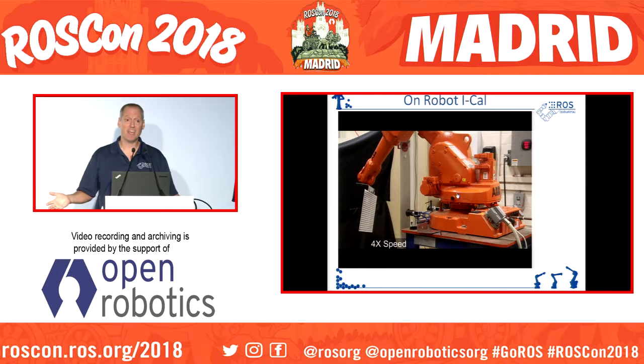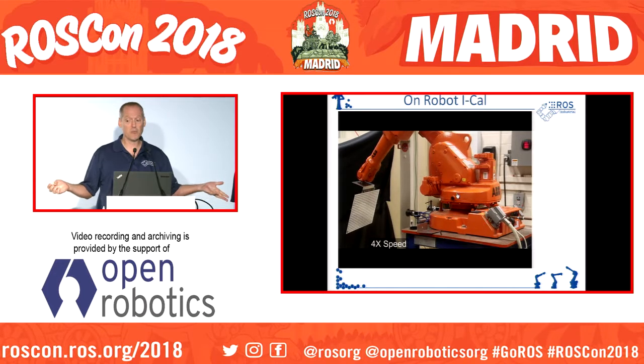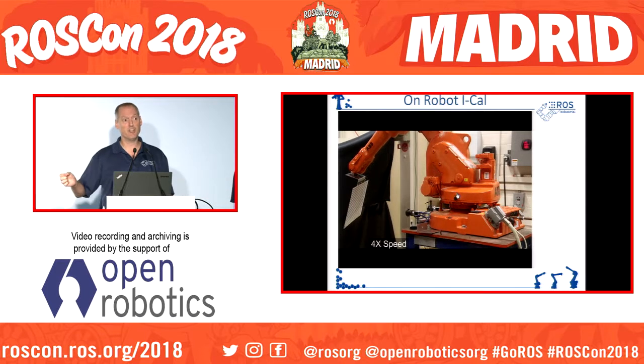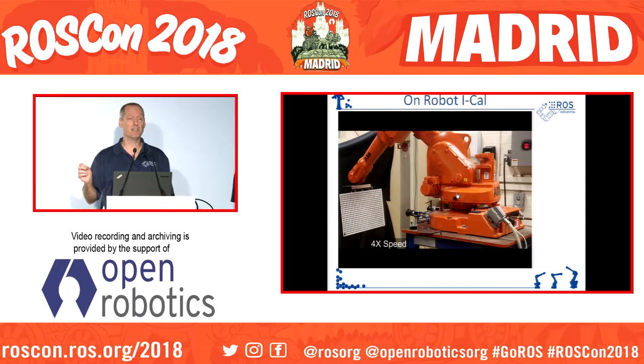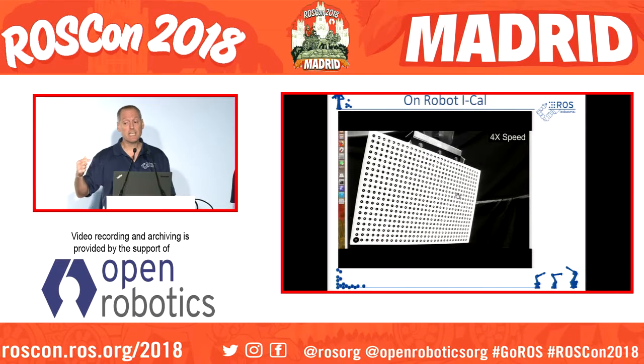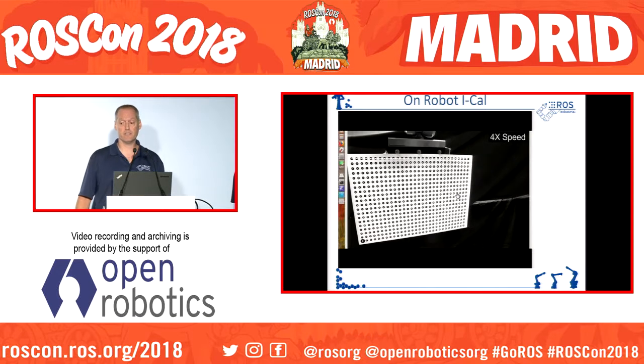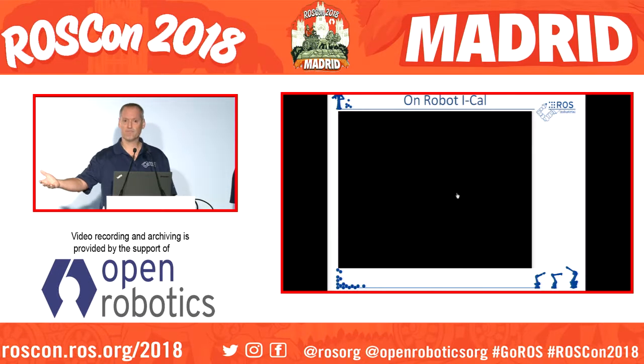And we do the same thing in terms of intrinsic calibration using a target on a robot. So it's a different node, different package, or not package, different node. But it has the same exact type of service calls, just a different base name of what this is. It says take a picture, and then you have to move the robot, and it takes the picture again and add all the observations you want. Compute your covariance whenever you're ready, and then see if you're good and add more pictures if you're not.